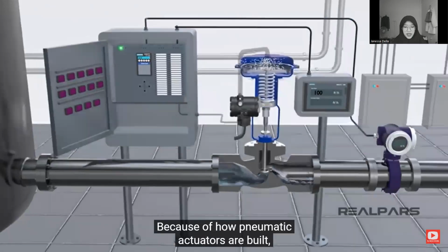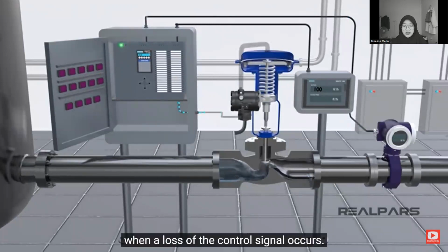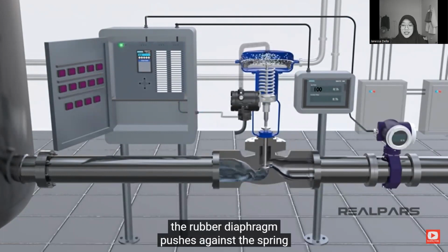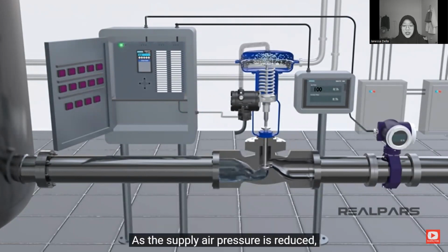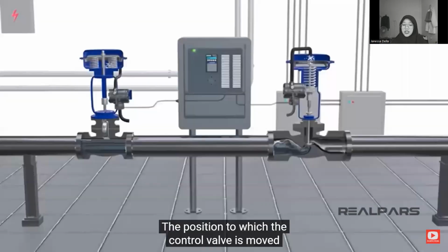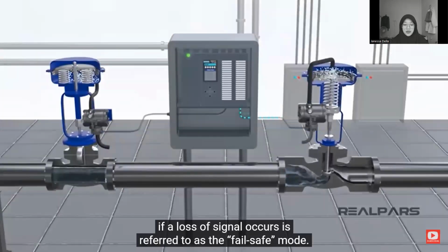Because of how pneumatic actuators are built, a control valve will fail to a specific position when a loss of the control signal occurs. As the supply air pressure increases, the rubber diaphragm pushes against the spring and moves the valve stem down into the valve body. As the supply air pressure is reduced, the spring will move the valve stem out of the body. The position to which the control valve is moved if a loss of signal occurs is the